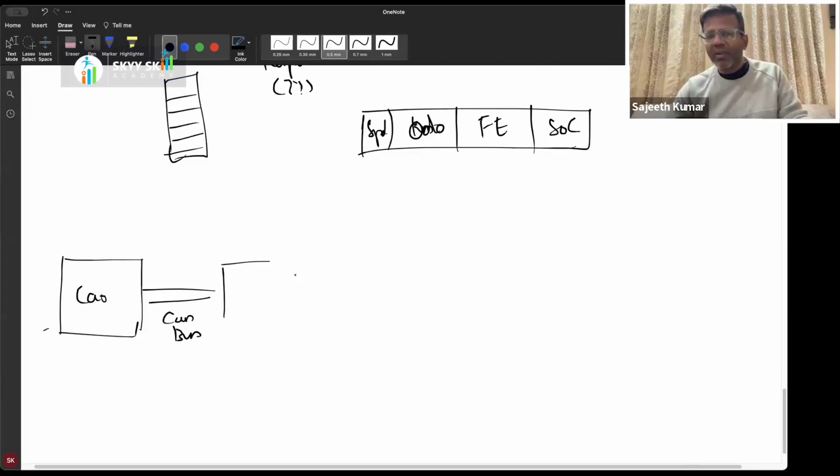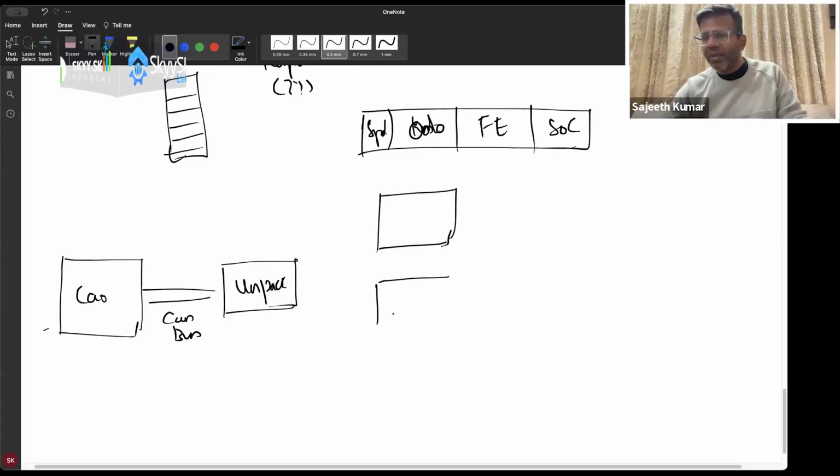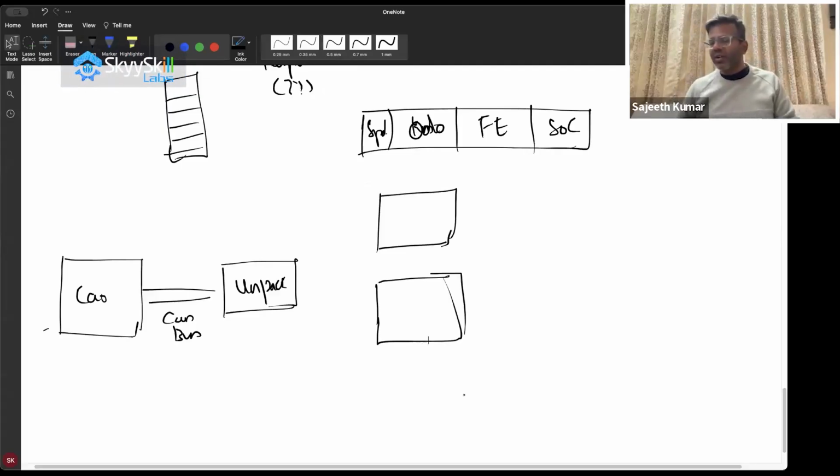The first step is to unpack the CAN messages, right? Once we unpack, there are a lot of things we could do to analyze the signal. You should not directly take it and try to feed it into a large language model. It does not work. It's very difficult for large language models to handle it. So we need to pass it into something which the LLM can understand.